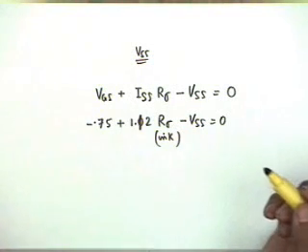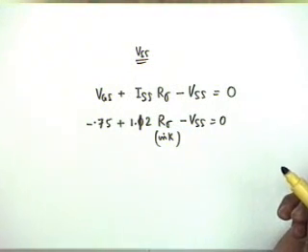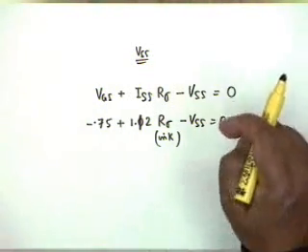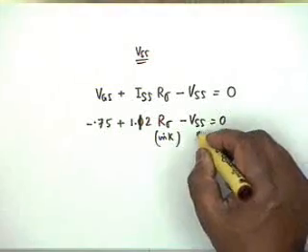Now the point is, from one equation we cannot determine two quantities, but it's a problem of design. Therefore you should be happy, you can choose one according to your convenience. Now if you have chosen VDD to be equal to 16.95, there is no reason why VSS cannot be minus 16.95 volts.